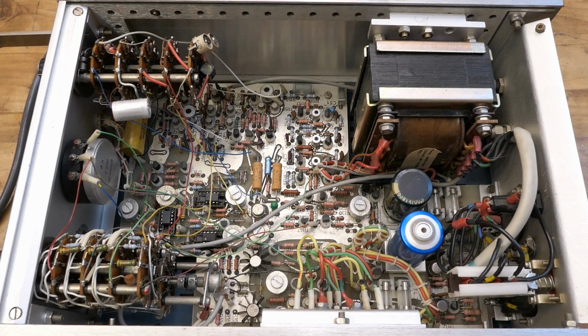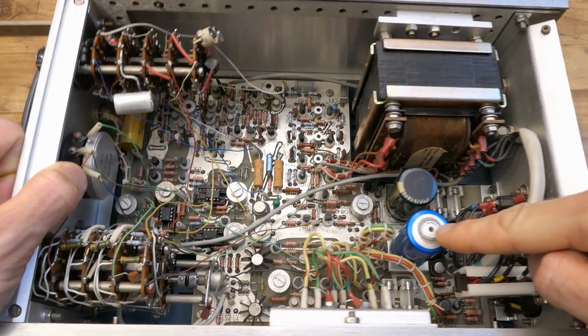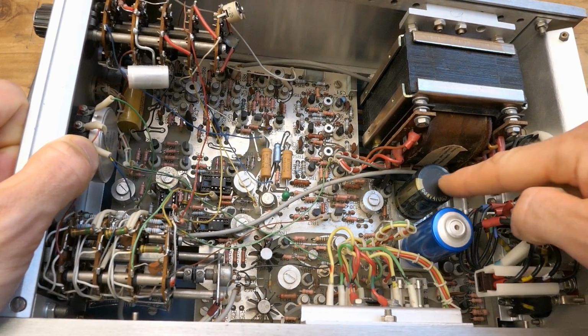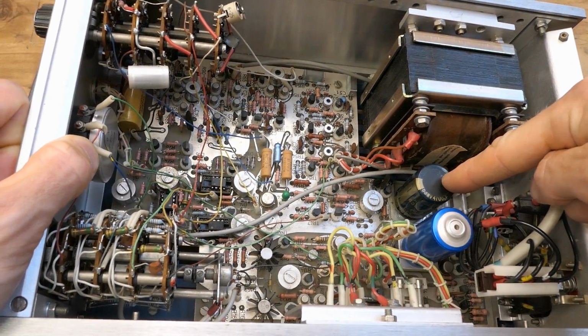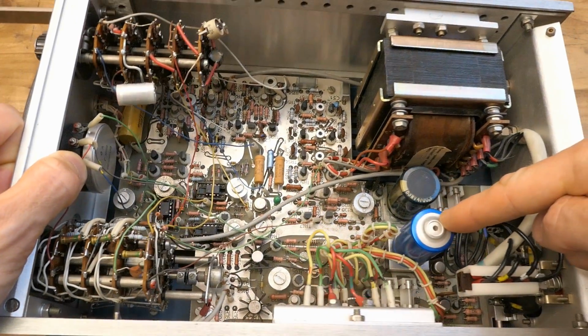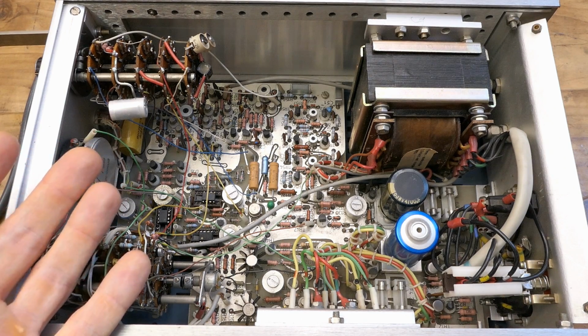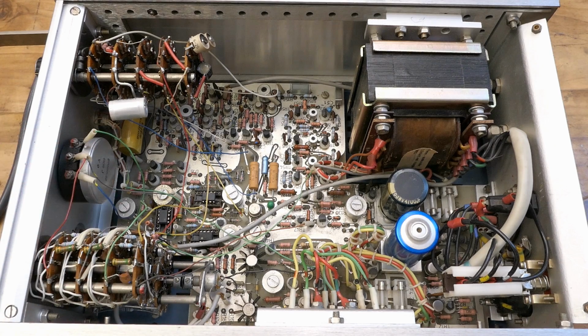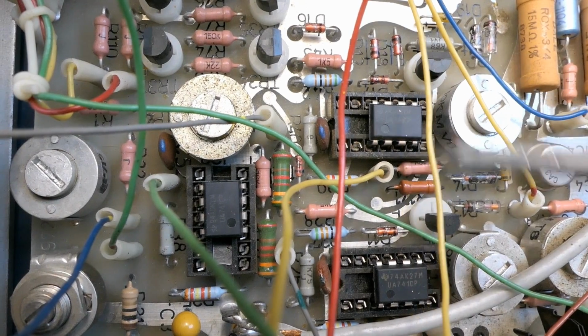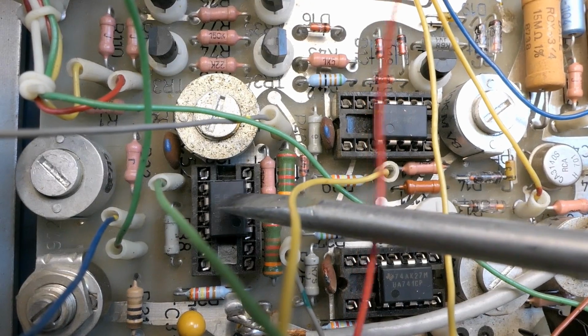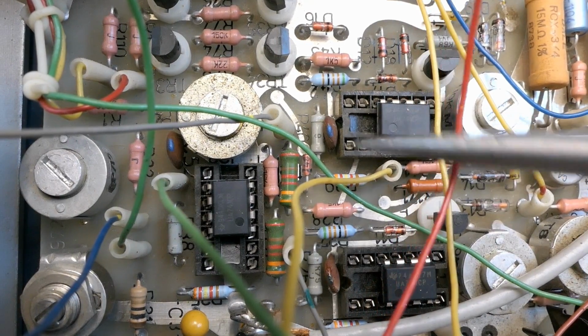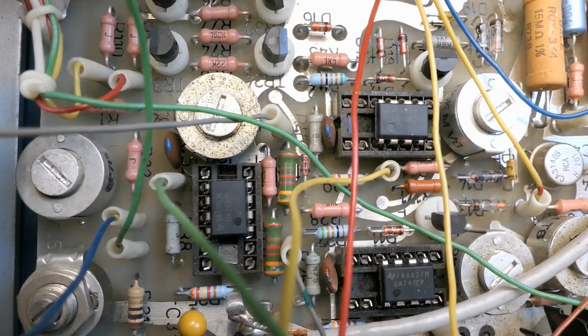And the power supply has 2 main smoothing electrolytic capacitors here. One of them seems to be replaced, it's a modern capacitor, and the other one is original old capacitor. And this was also done by the previous owner. I don't really see any other obvious modifications in it, it seems mostly original. Other than these 3 OpAmps in these sockets, 8-pin chips basically in 14-pin sockets. Not sure what this is meant to be.